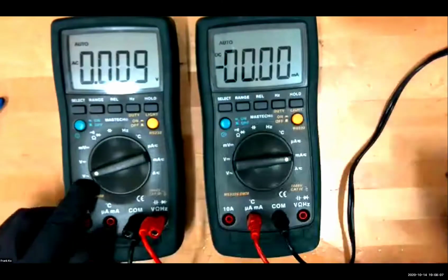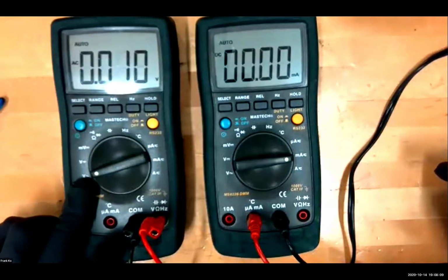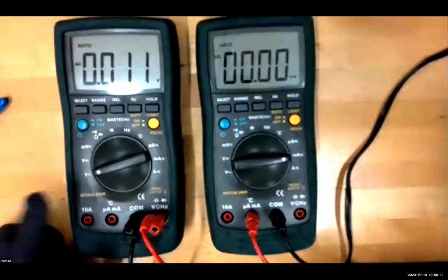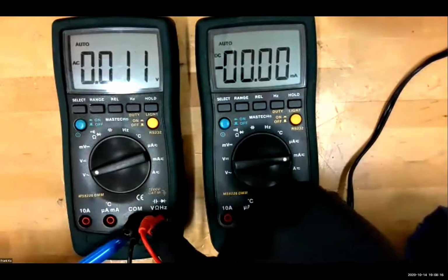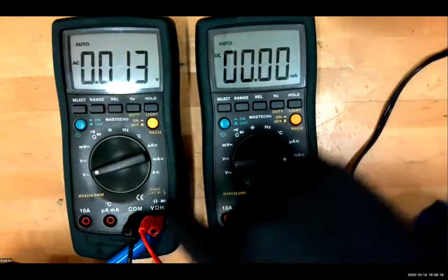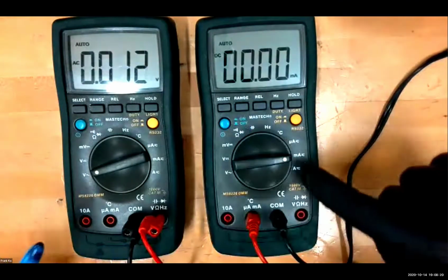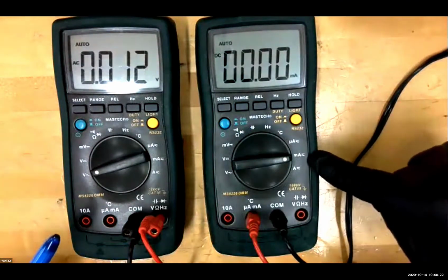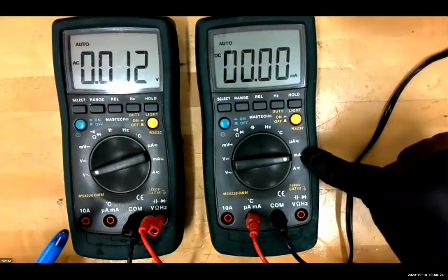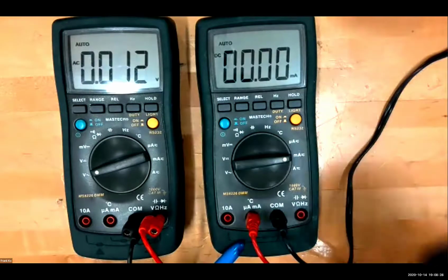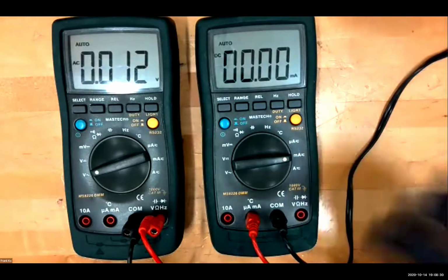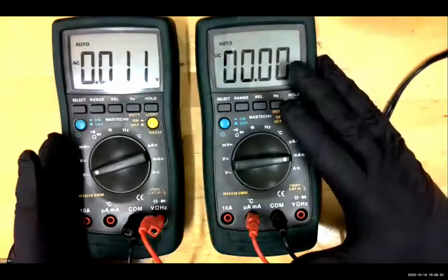So is this guy set to measure AC voltage? It's on. Let me focus. There. Nice. AC voltage, and this is set up to measure voltage. Red is on V, black is on common. Is this guy set to measure current? AC current, milliamps. And is the red over to the milliamp connector, and is the black on common? So you got to get your meters set up so that they're ready to go.